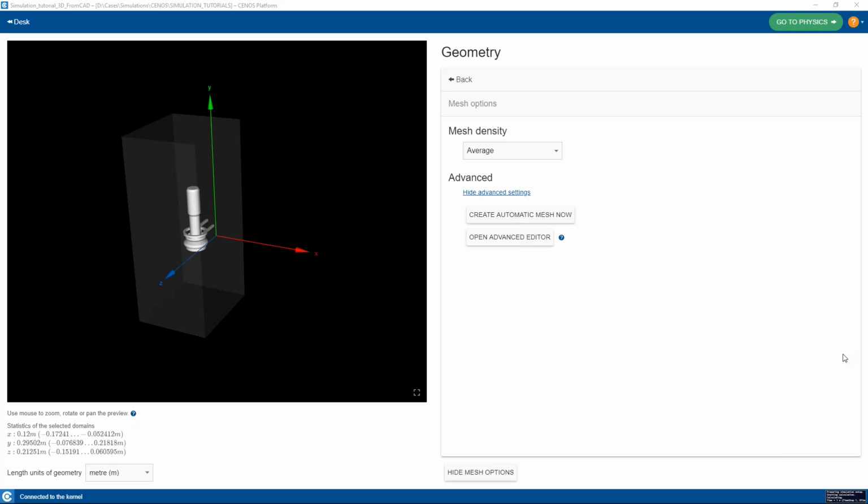Yes, I understand the idea. We have actually talked about this, but not from the perspective of current or frequency, but of the heating time, in a way that you would not set the end heating time, but you would say that you want the maximum temperature to be, let's say, 800 degrees, and CENOS simply stops when the temperature has reached 800 degrees.